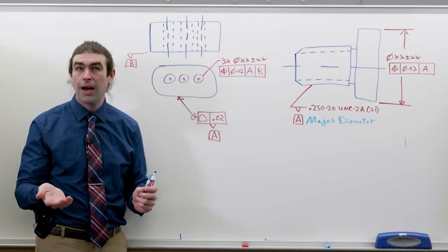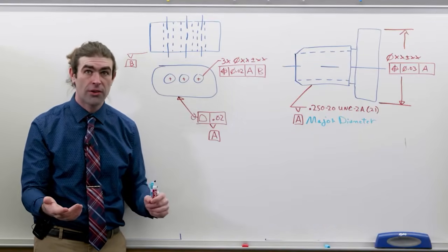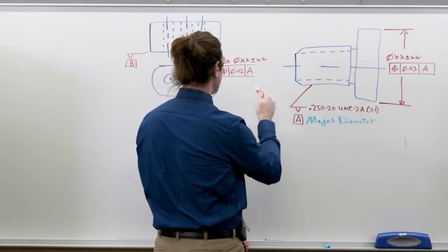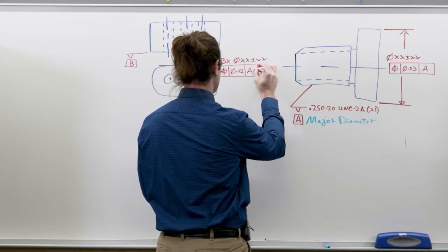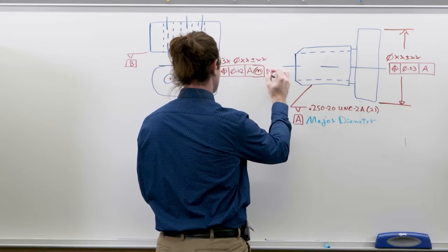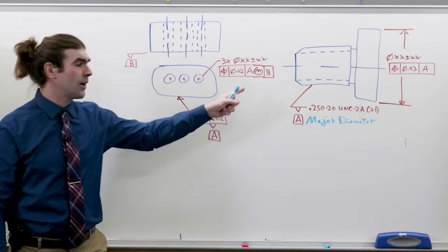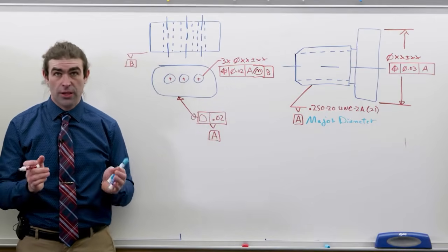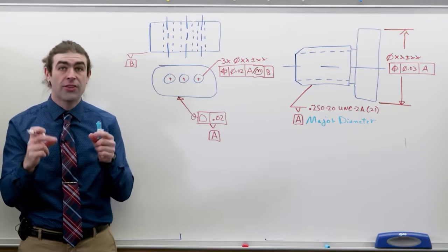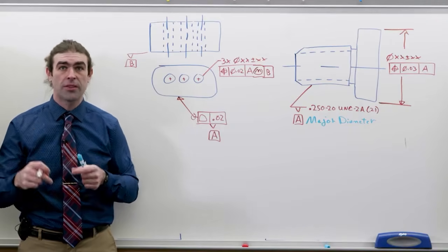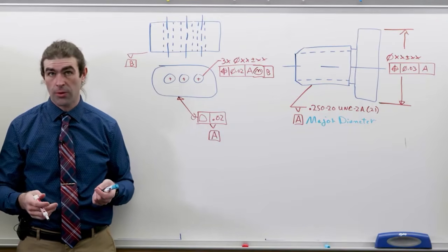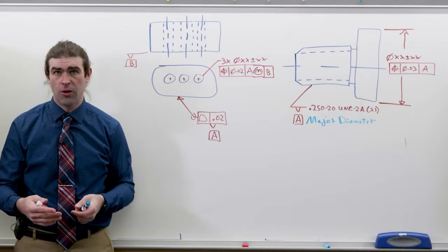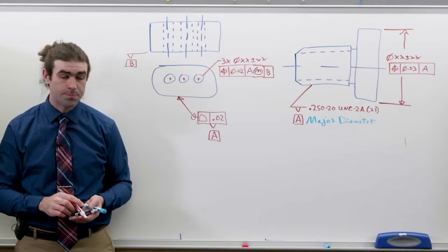That kind of stuff is possible to produce for inspection, but generally, unless you have a really good reason not to, you want to specify that at MMC or MMB so that they could make a slot shape, drop it in there, and then check the position as normal. Okay, so basically the part can rattle around a little bit. I have another video about that. I'll put a title card up.